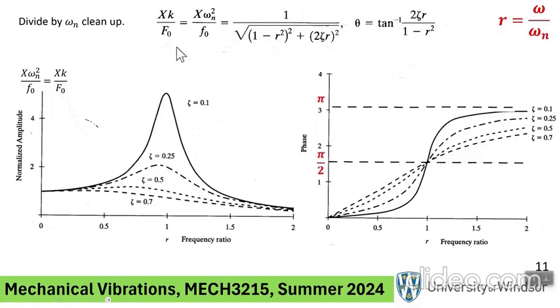So, for example, look at it like this. When damping is very light, when there is no damping actually, you get 1 over square root of 1 minus R squared squared, or 1 over 1 minus R squared if you take the absolute value. And what do you know?